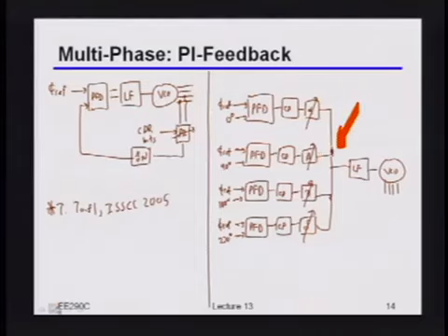By the way, I should also mention this was done by some folks from Rambus. It was first published in ISSCC, but the journal paper is from John Poulton, in JSSC, December 2007. And this was for one of their first low power link kind of things. There are lots of different potential ways you can do these things, but the ones we've been talking about over the last couple of slides are really nice when you have heavily multiplexed systems where you need to generate multiple clock phases all with the same controllable phase offset.